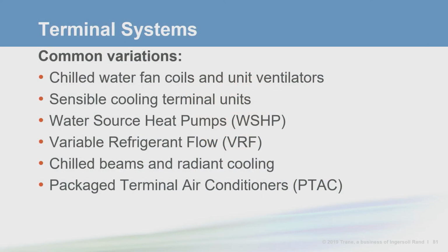Now that we've covered the ventilation system in detail, let's discuss economizing options and some unique code or standard requirements associated with a variety of terminal systems. The choice of terminal system varies widely, but we'll cover some of the more common systems in what follows. Here we'll discuss a few fan coil variations, some systems that are capable of heat recovery, sensible-only terminal systems, as well as some compressor bearing systems.